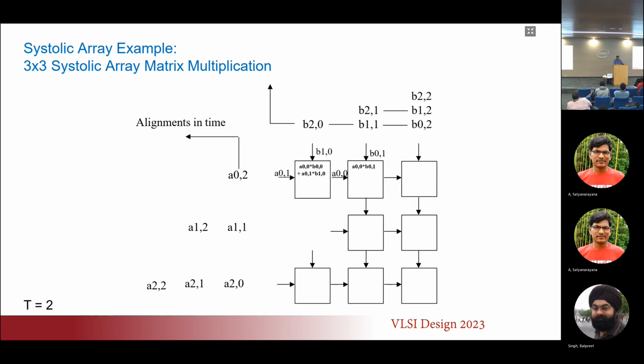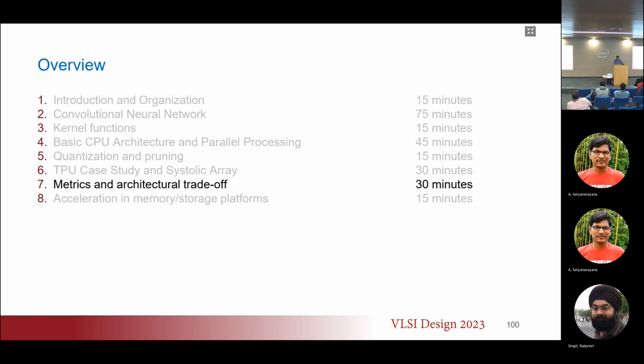So we did that, and I'm not spending more time on the TPU analysis. I think I've already explained that this is a design decision that Google made. First, they're trying to speed up only classification, not training. Second, that's why they did 8-bit. Second, they had a limited set of applications. They could preload all the weights into that DDR3 memory that you saw, which is local to the TPU.